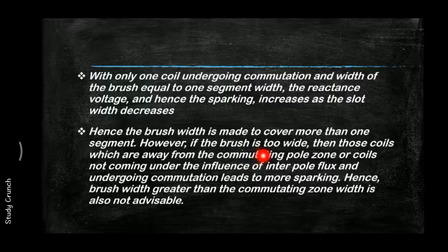However, if brush is too wide, then those coils which are away from the commutating pole zone, not coming under the influence of interpole flux and undergoing the commutation, lead to more sparking.